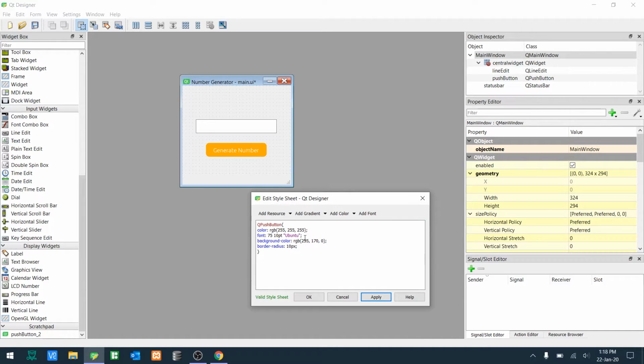Okay, that's really good. If you change your button to, let's say, 35 round, and click apply, you see it becomes a rectangle again. That's because you over specified. That means it cannot go over 35; 35 is too much. Maybe let's say 25. Same thing. So maybe let's go 15. 15 should be okay, I guess. Yeah, see, 15 is round. But if you specify it too much, then it just ignores this line because it says no, you're wrong.